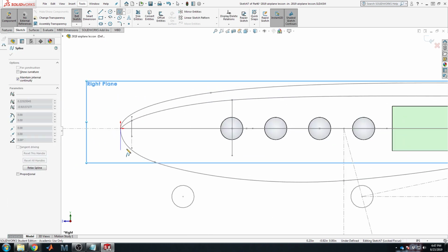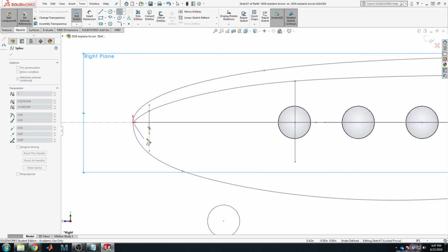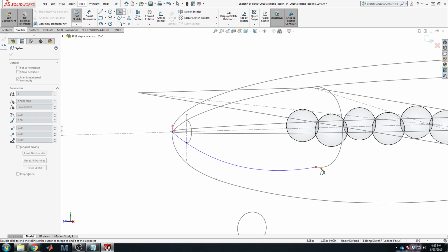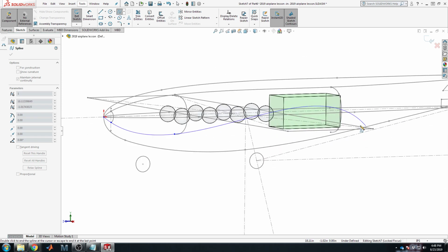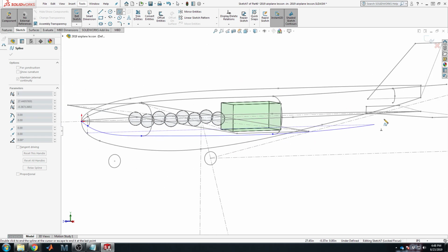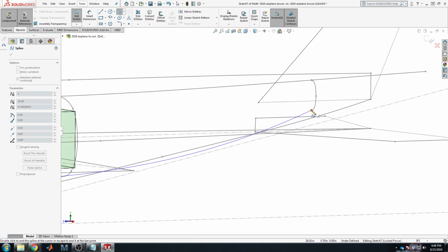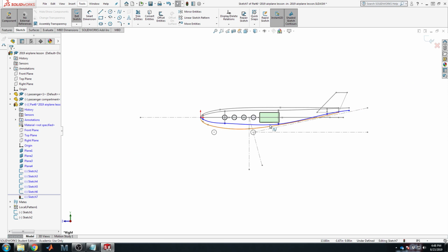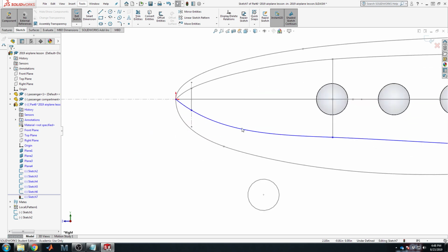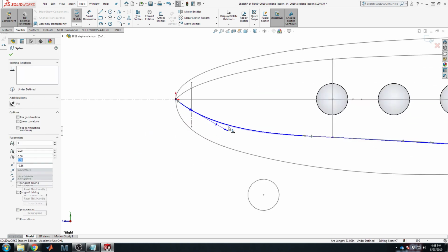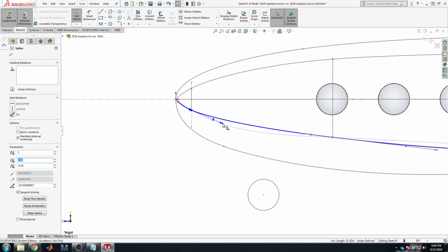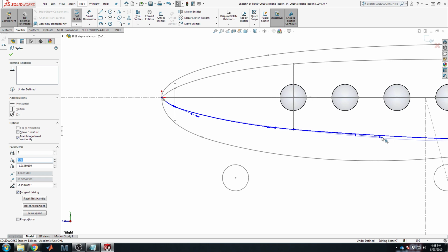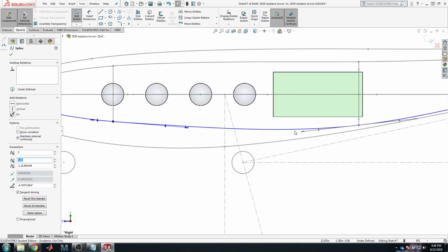And this is for the same reason we do airfoils top and bottom, to be able to select the path top to bottom each, because these are going to become guide curves for the loft. We're going to make this surface pass through these lines, which gives us better control over the shape that's actually generated. So if you're from the side, you can see this one obviously needs some shape control. So let's do that with the handles. Much better to do it with handles than with just numerous additional points.